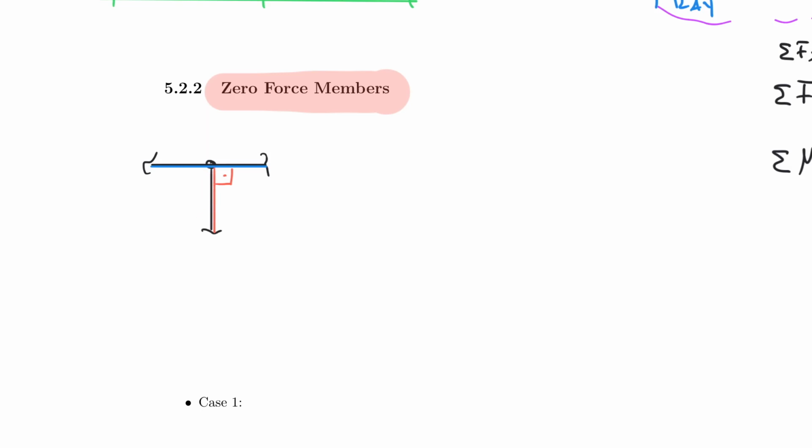And therefore this actually works for any scenario, not just for the perpendicular case, but I can have the very same scenario. So let me redraw the system here, and let me join a third one, which now is actually under an angle. And often students think, now it's under an angle, it cannot be a zero force member anymore. But remember, we cut through the system here and here and here, and the red component, the one that is not parallel with the other 2, actually has a vertical component and has a horizontal component, something we dealt with very early in this class.